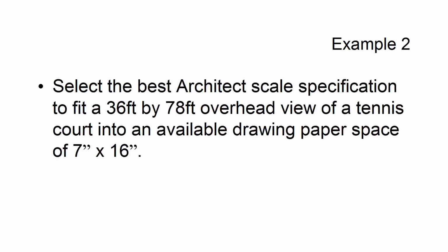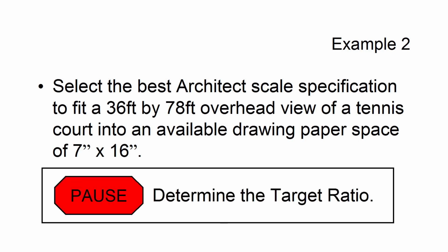Example 2. Select an architect scale to fit a tennis court overhead view, 36 feet by 78 feet, into an available paper space of 7 inches by 16 inches. Go ahead and pause the video and please determine the target ratios along each direction.